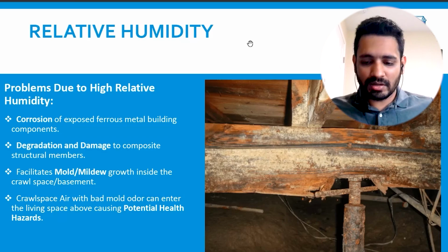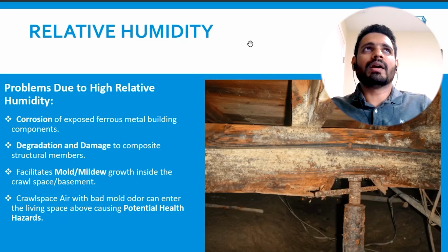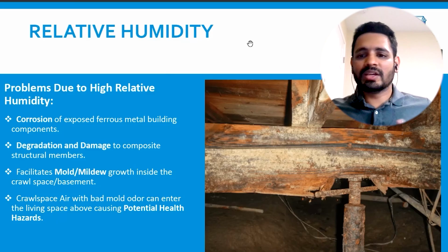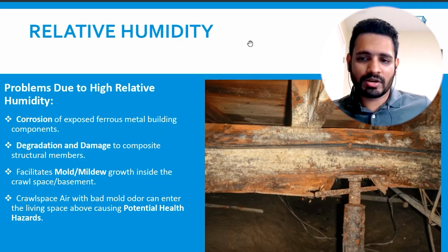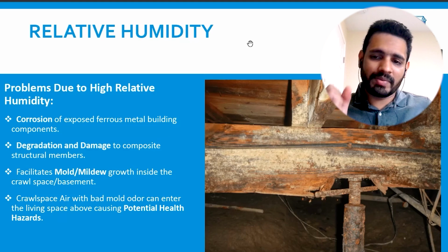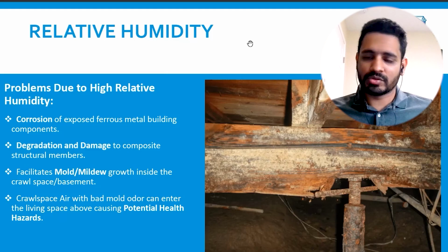You could see a lot of metal jacks in Santa Clara. You could see a lot of them in the Milpitas area, around the late 60s and the entirety of the 70s. I think engineers thought, let's try out some metal jacks, because at a capacity level, these metal jacks are much higher rated than what a 4x4 or a 4x6 wood post would be able to handle.